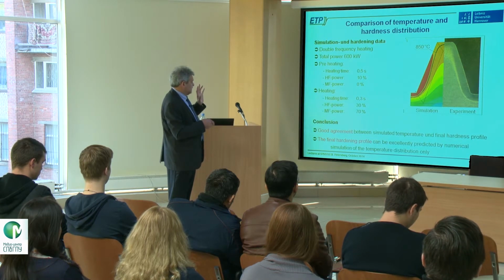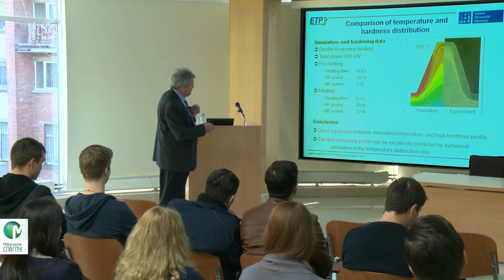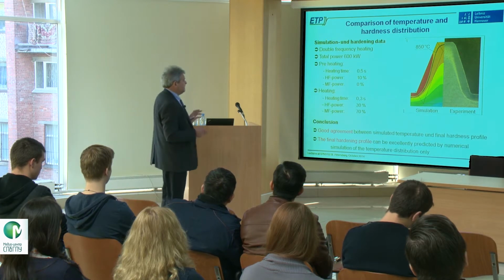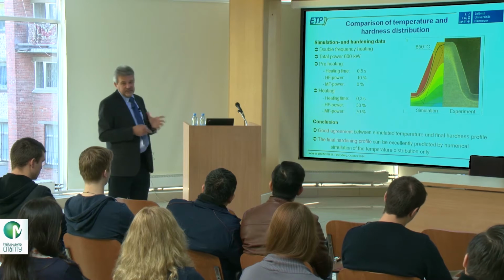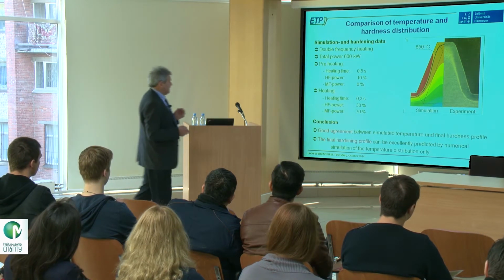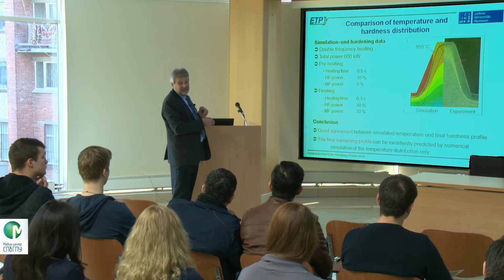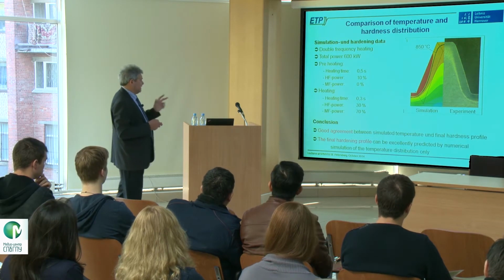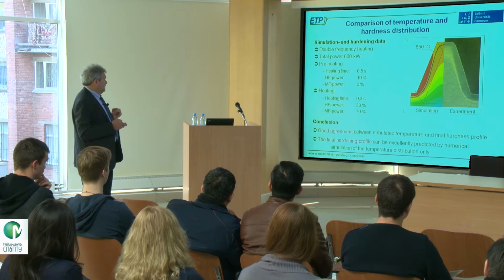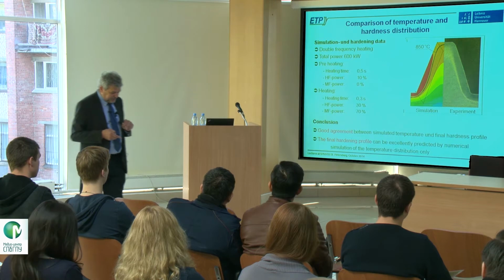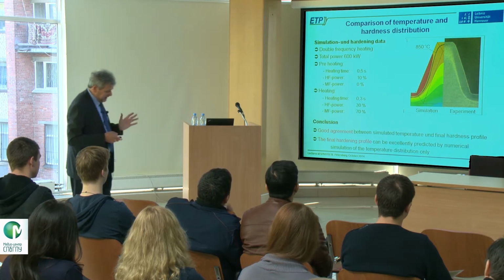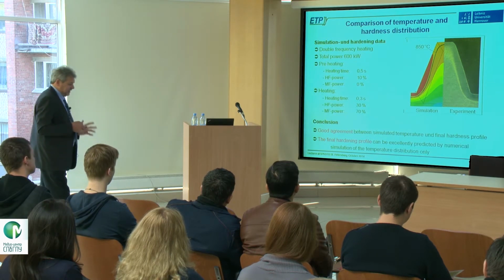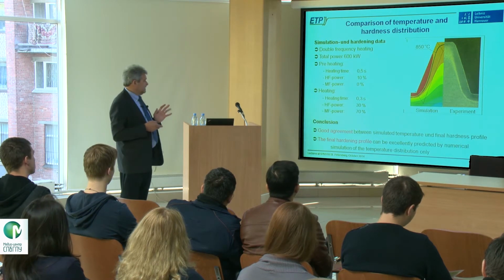Today we know that it's true for such applications where the hardening depth is very small, but for larger hardening depths, here it was 0.5 millimeter, for some millimeters it does not fit so well because the cooling is then less effective inside the material. Therefore today we can also realize the simulation of the hardening profile, of the material conversion, at least with some approximative methods. It's not so exact like temperature and electromagnetic simulation. So you see this is also one example of electromagnetic processing of materials here in the area of solid materials, only by heat, by applying heat very fast to the material and then changing the material properties, like in this hardening profile.